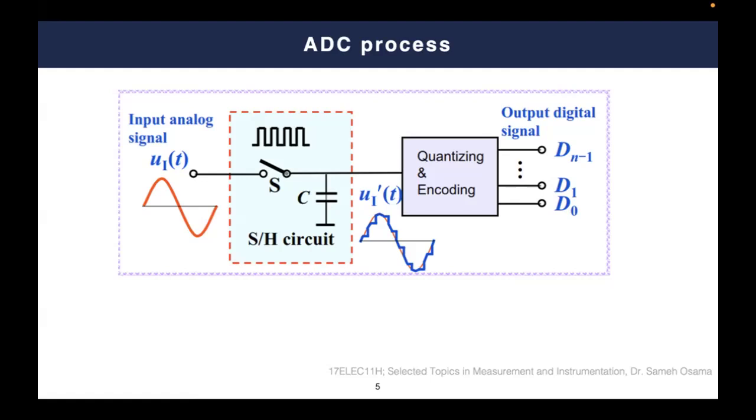And in this simple way, you can understand the main processes of the ADCs: sampling, where we are discretizing the time axis; quantization, where we are discretizing the y-axis; and finally encoding, where we transfer this system, discrete in both time and amplitude, into code, into binary representation. And this is the general model or methodology for an ADC.